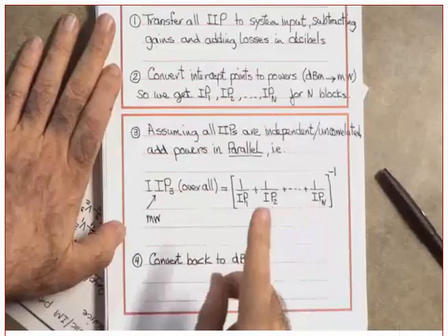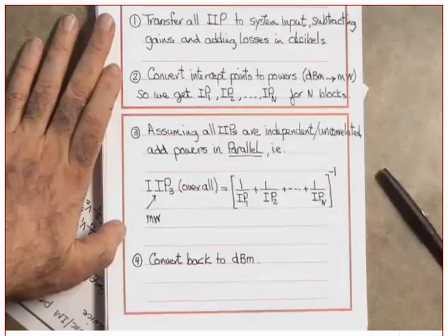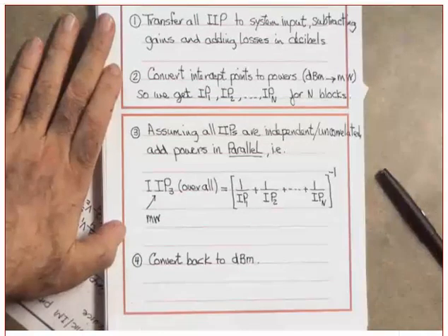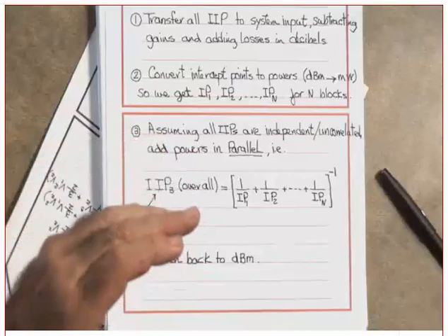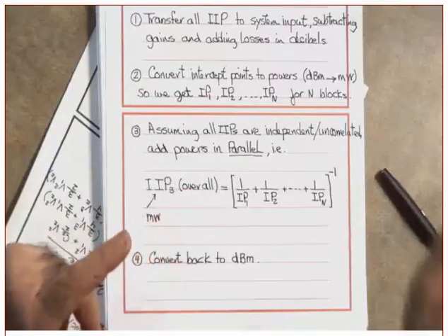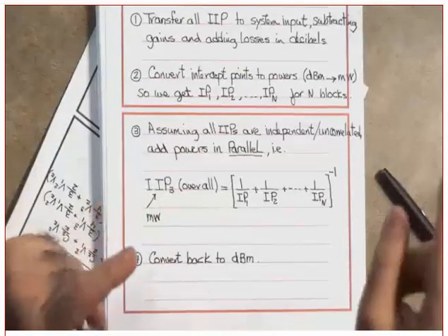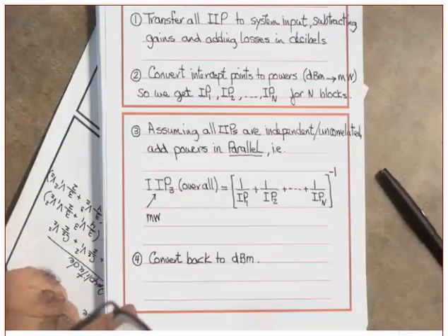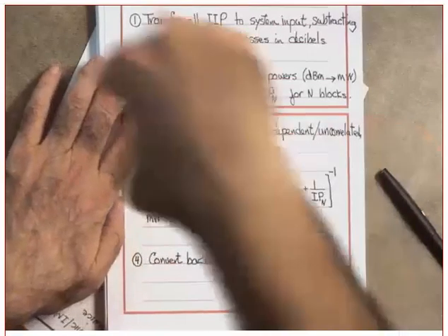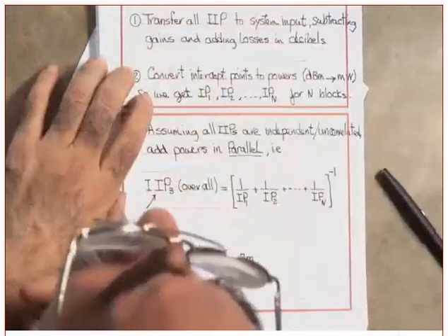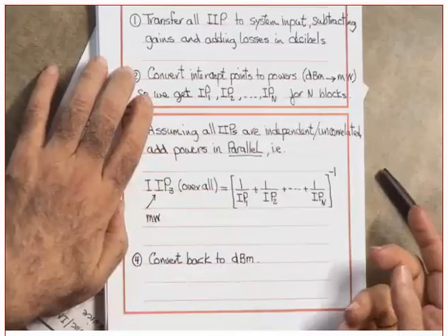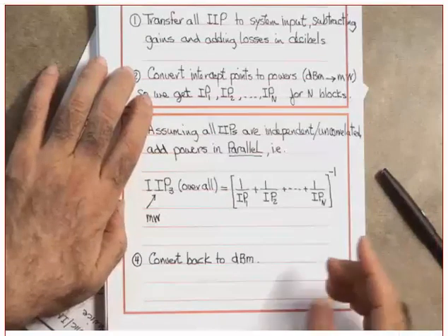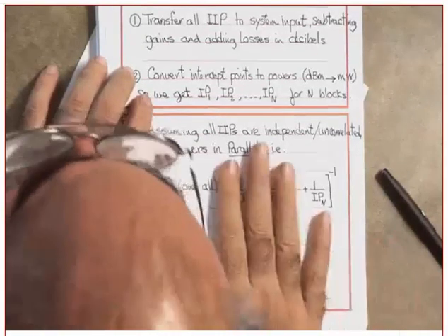Clear? Okay. You need also to be careful if the question gives you IIP or OIP. Do you understand that or not? Because if it gives you IIP, the gain of that system will not get into the picture. Do you agree? But if the question gives you the OIP, you need to take that gain into the picture to get the IIP. Yes or no? And in the midterm, I will give you a mixture so that I fool you. Do you understand that or not? You have to remember, I'm a mean guy. Did you get my point? Yes or no? I don't think so.